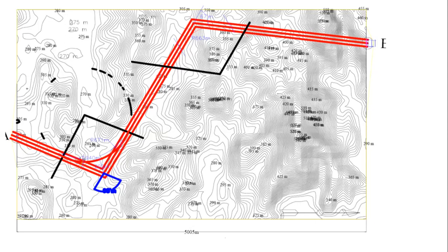So if you think there is no development, actually there may be, because the AutoCAD drawing that you have been provided may have these layers switched off. So toggle all the switches on and then see your topographic map. These are the two things that will help you determine the terrain type as well as the area, rural or urban.